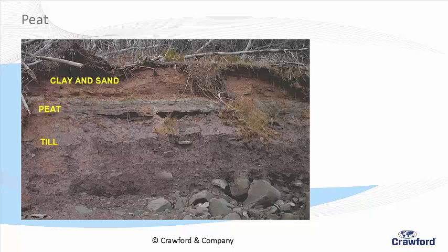And if you get a thin band of it, fine, it will just compress. It's like squidgy. It will compress and the moisture just pushes out. That's fine, and you get a little bit of subsidence. But we've had situations where we've got 6 meters of peat. So you know this thing's going to carry on for a long time. And where you have that, there's no reverse in the movement, unlike clay. There's nothing you could do to mitigate, like take a tree out. So you're probably in for a bit more trouble there.